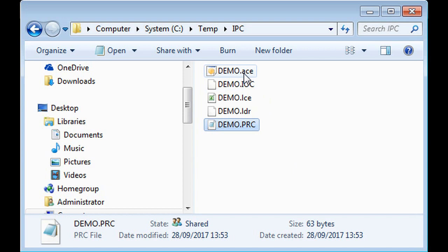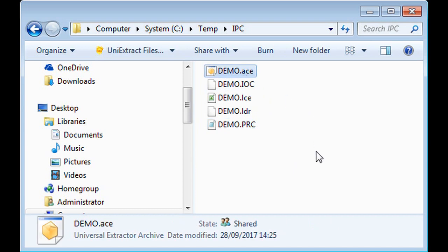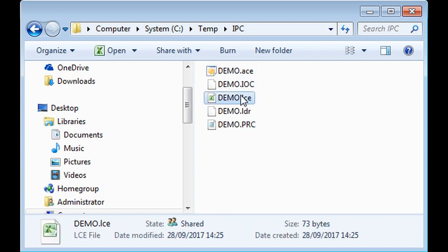Again, if you're using a communications port for Modbus or Honeywell IPC communications, this file is quite important. The other files that we see here, ACE are address comments, LCE are line comments, and another one you may see would be LBL, which is label comments. You don't need those three files in order to load and run the PLC program, but obviously having labels and documentation attached to your PLC program makes everything much simpler when it comes to diagnosis of problems.